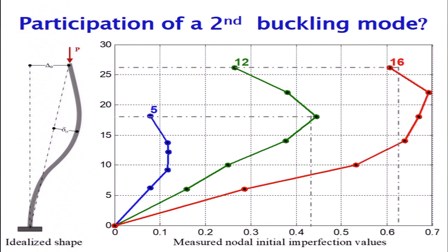You would think that the eccentricities would be very small, but in fact, if you have something that's 26 feet or 8 meters high, and you are trying to put it on a fixed base, you can never weld it perfectly, and the tube itself is not perfect. So all of these imperfections were also put into the analysis. The only thing we couldn't really put into the analysis were the actual residual stresses. We actually tried to put some residual stresses that come from the literature, but we didn't have the actual residual stresses in our analysis.